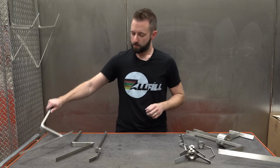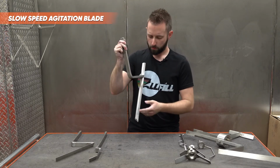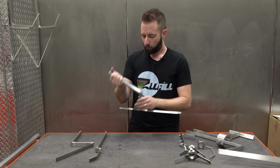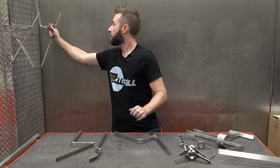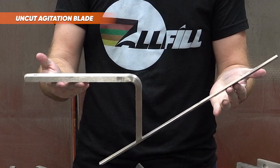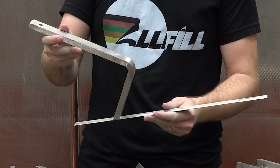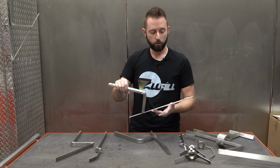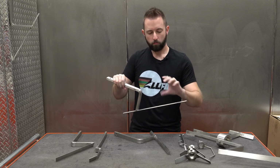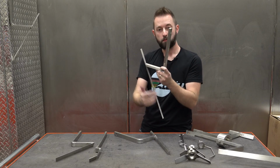So starting on the right side of the bench here, we have our standard slow speed agitation blade. These are cut from blanks that we manufacture here at All-Fill, which I'll show you what that looks like. One of our standard uncut agitation blades looks just like this, and you can see the blunted edge on it. So essentially this gives us the ability to figure out what size auger and tooling you're going to have, and we'll cut it specific to the overflight of your auger so that the agitation blade doesn't hit the auger.